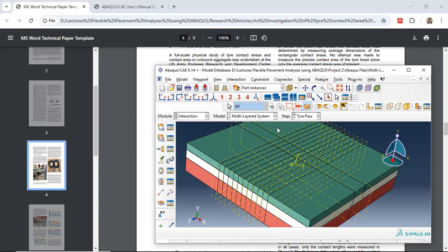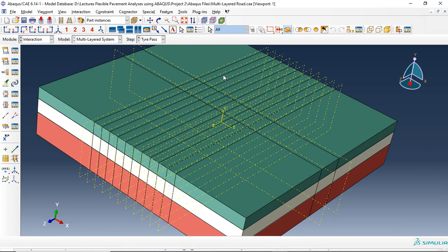So these are very important, and for real-world pavement testing, if you are working with experimental data, you need to be careful about it. If you are working with ABAQUS, you need to define the tire patch as a pressure distribution. It may be parabolic or trapezoidal over a rectangular or elliptical area. You can also use analytical rigid surfaces or a deformable tire model to simulate contact. I will try to do that. And you can also apply dynamic loading or rolling conditions to mimic moving loads, which I will also try to show in some of these projects.